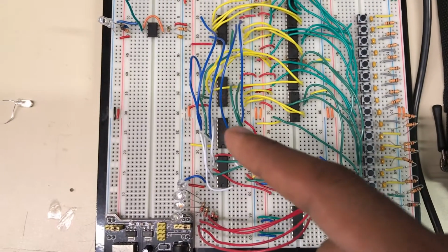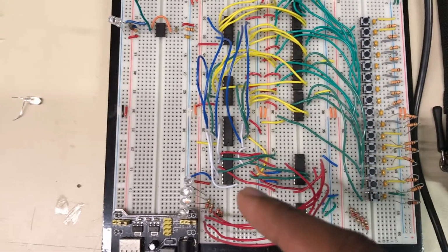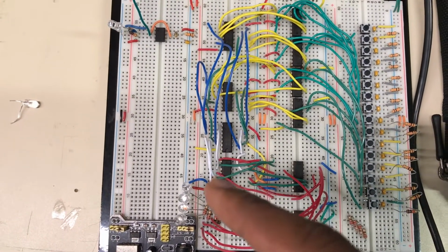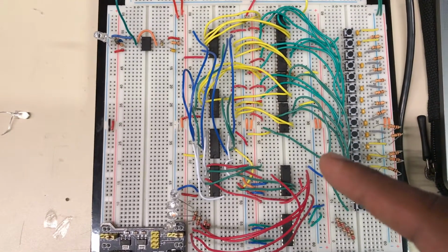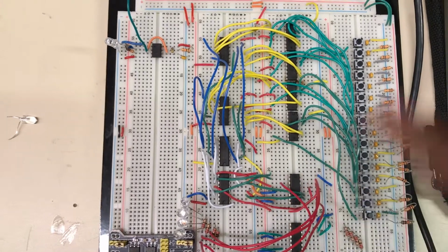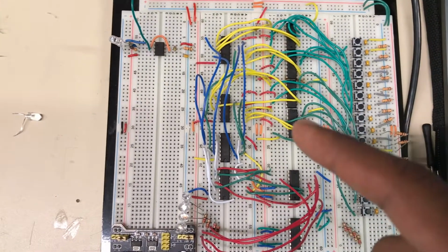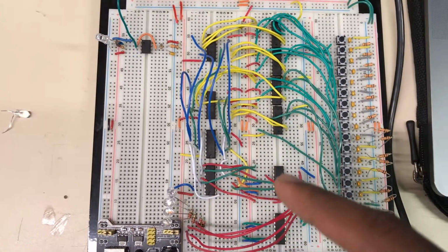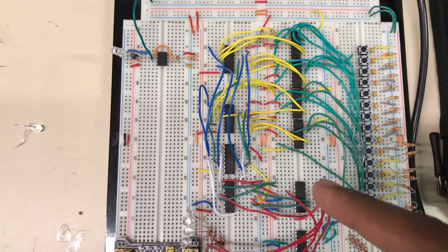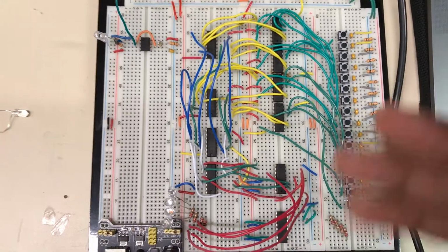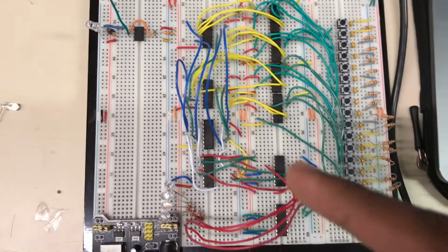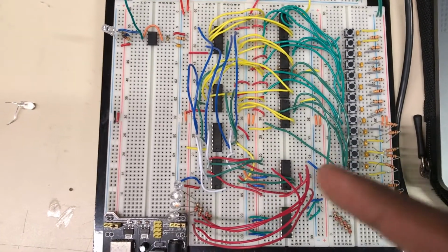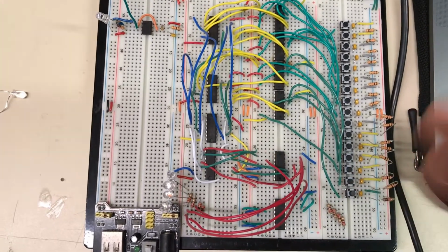Then these 4 bits of data are, using this multiplexer here, stored and held in this register. The purpose of the multiplexer is when you press a button and you input a floor into the circuit, you want the register to hold the value of that floor until some condition is reached. And so the idea with the multiplexer is that it'll continue to hold the value of the floor, and it won't release it until a new...